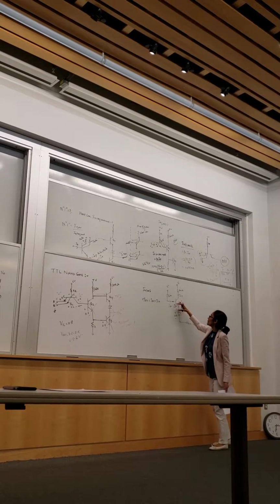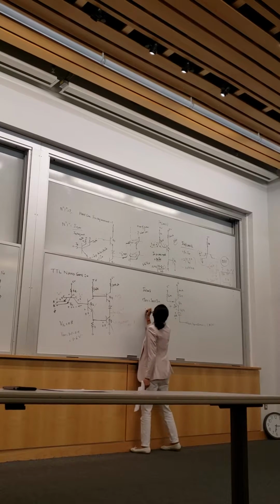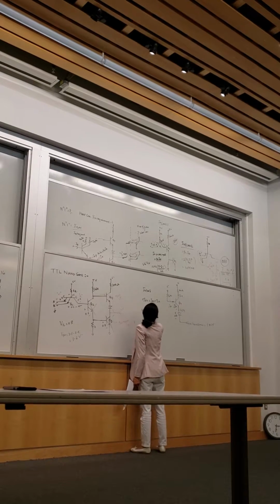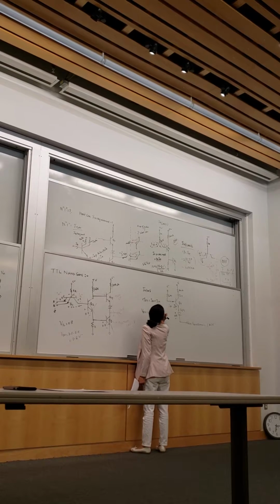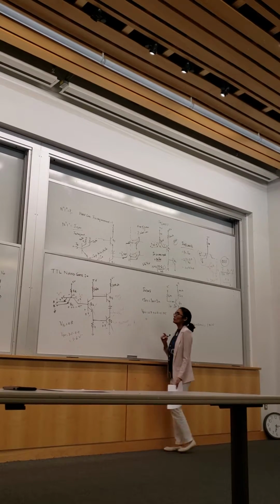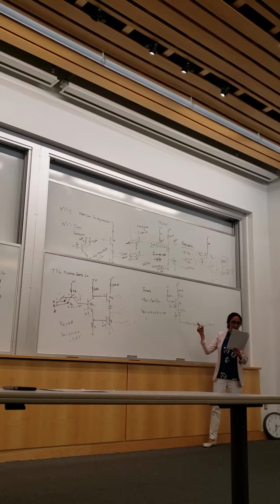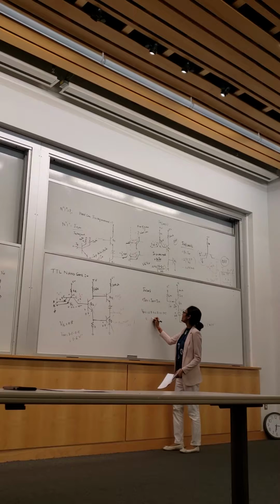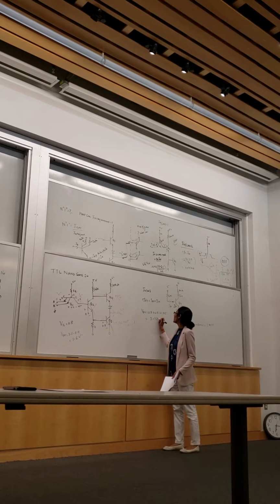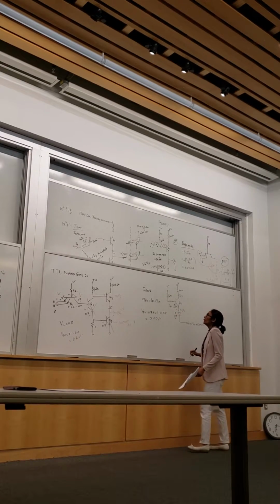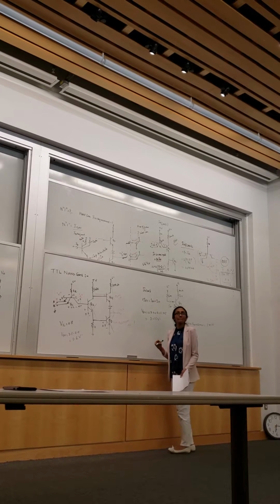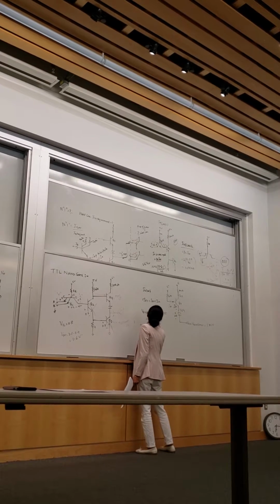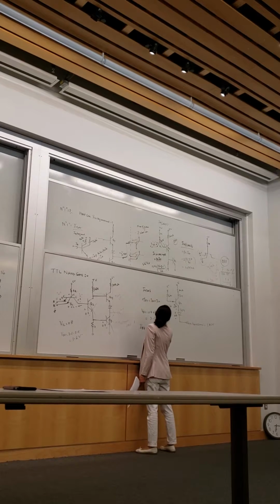KVL. This voltage equals this plus this plus this, right? So the voltage at VB4 is 0.7 plus 0.7 plus 1.75 volts. What's the value here? 3.15 volts. Now, can we get IB4? Yes. Okay, IB4 is 5 minus 3.15 divided by 1600.